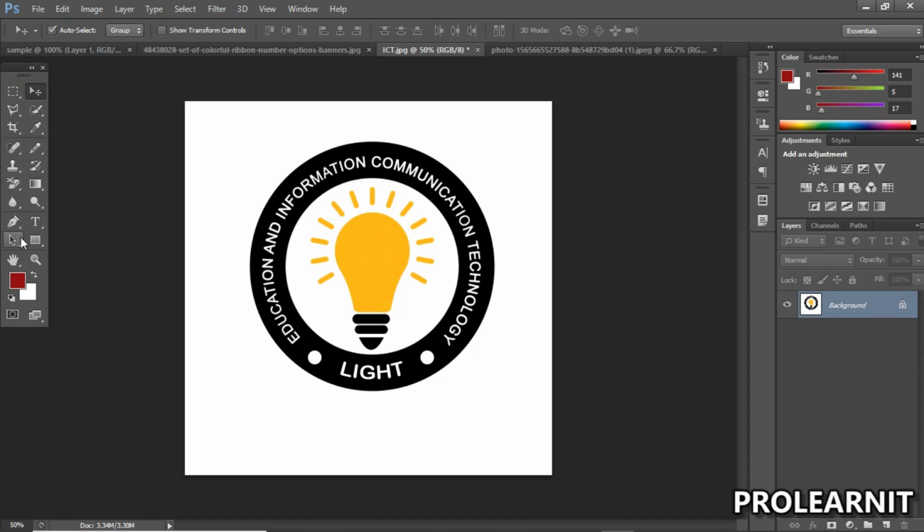Alright friends, at this juncture I'm just going to be teaching you about the background eraser tool, this particular tool right here. That's what I'm going to be teaching you in Photoshop right now. Without wasting much of your time, I click on the particular tool, and if I left click and hold, you can see what we have over here: the eraser tool, the background eraser tool, and the magic eraser tool. Let me start with the eraser tool.